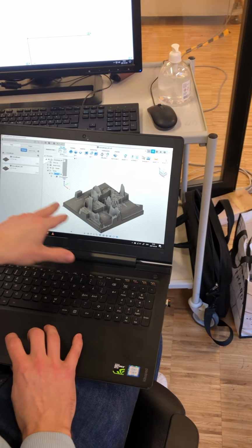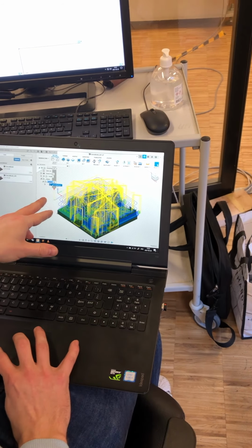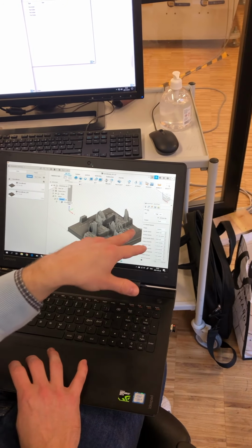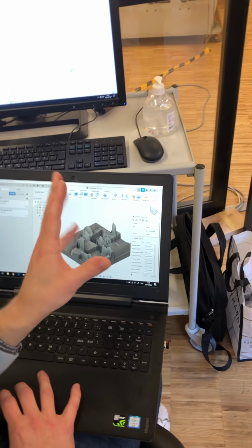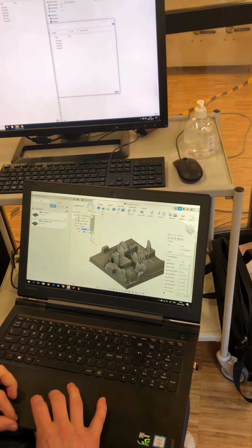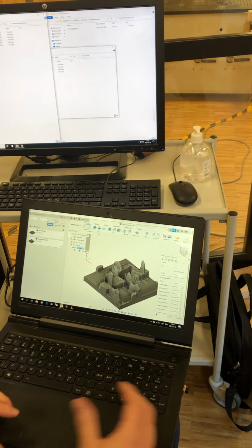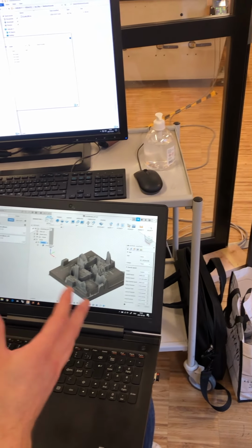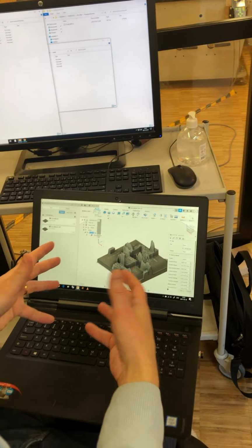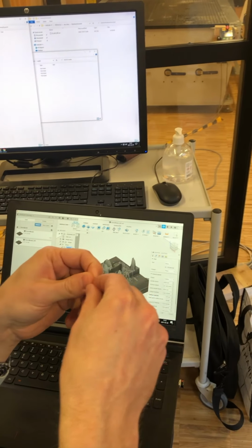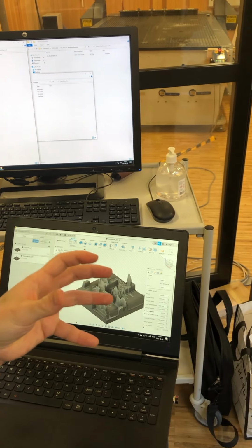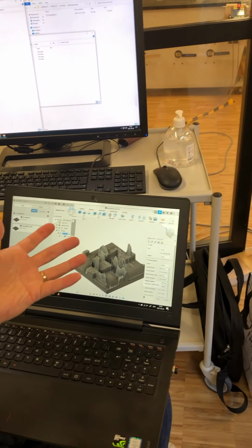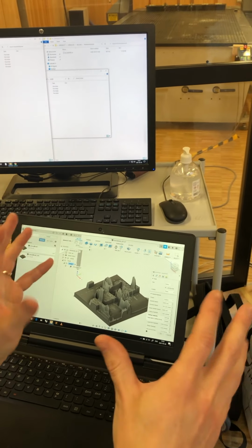One thing I will do now, when you double click on a toolpath here, you open the properties for it, and here you can change all the properties for it, and the tutorial goes through it. And if you have any questions, we can of course have a follow-up. So one thing I will do here, instead of using the toolpath that we actually used, I stated in the tutorial that the feed rate, the speed at which the router moves through the material, for styrofoam is good at around 3,750 millimeters per minute.